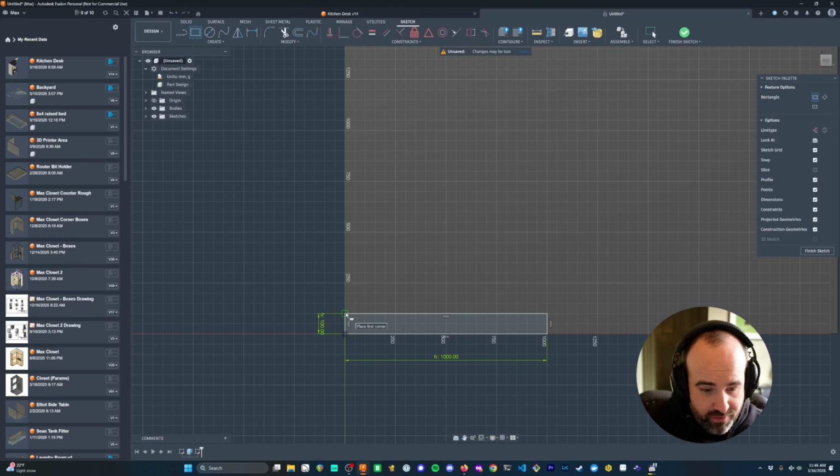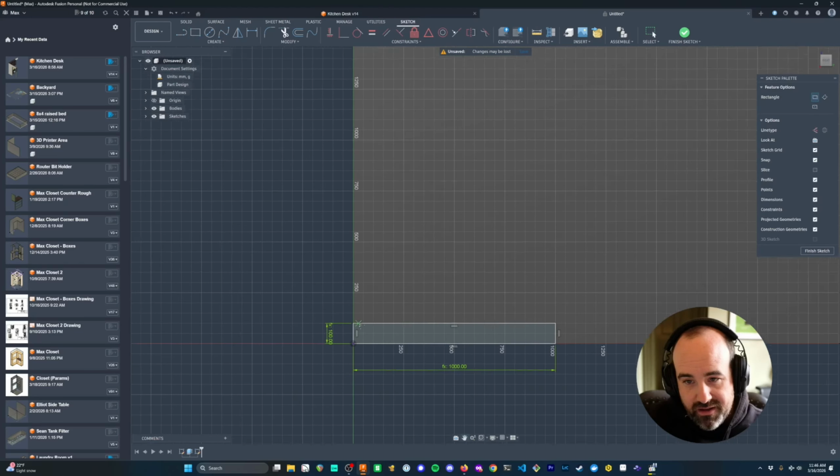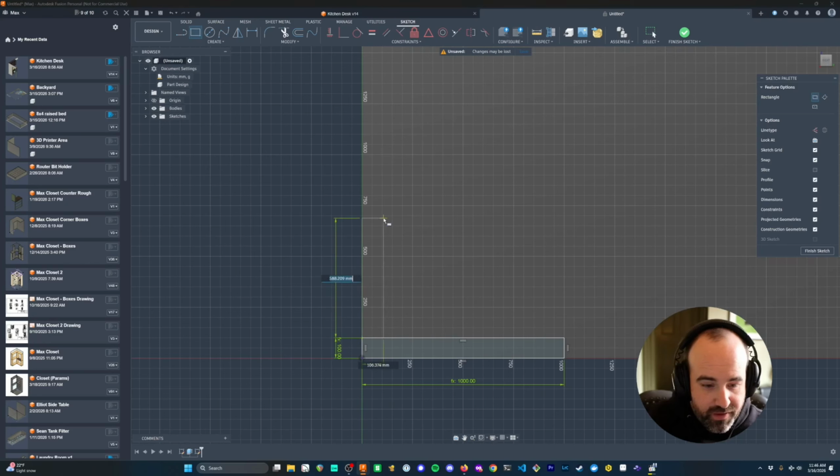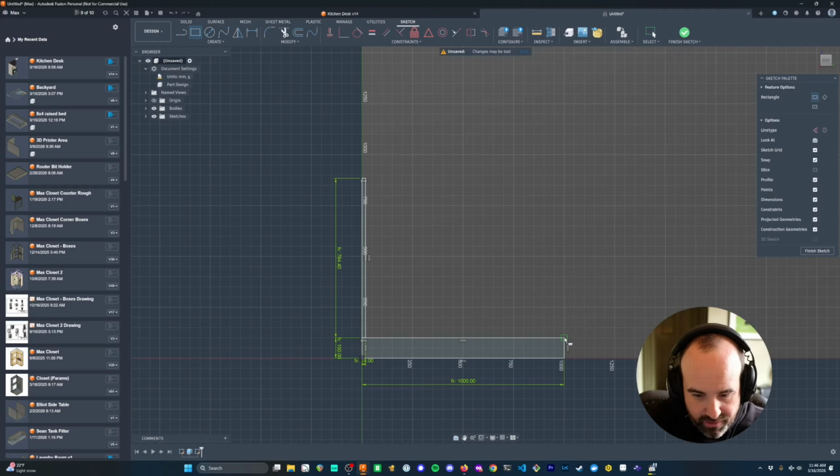And then I'm going to create the first 2 side pieces of the cabinet box. And so we have cab height, because those 2 side pieces are going to fit. They're going to go fully from the bottom of the toe kick to the bottom of the countertop. So we can fill that whole space. We'll do cab height and then ply thickness. And we're going to do another one on the other edge here.